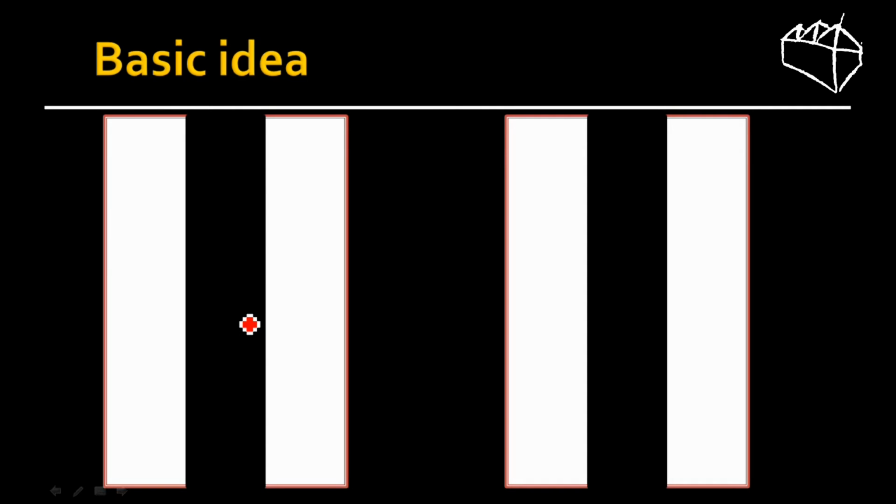And to begin with, I will show you how the simplest of all line followers would actually work. So you have a robot, and this robot should have one light sensor or color sensor, and it can detect the value of the light which gets reflected back to the sensor. For example, if the sensor is on this black line, it would receive a value of 0.